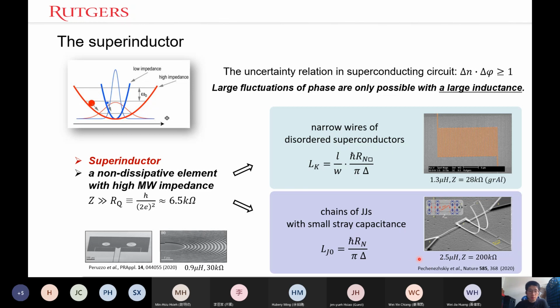Right? And both of them have some material-related property, which is the band gap of the material, but meanwhile experimentally, we just control the normal state resistance, which we probe at room temperature, for example, and we can tell how much kinetic inductance it will provide at low temperature when it becomes superconducting. So in both cases, the challenging part is that the parasitic capacitance must be minimized, and this figure gives us a quick visual idea about how difficult it has to be.